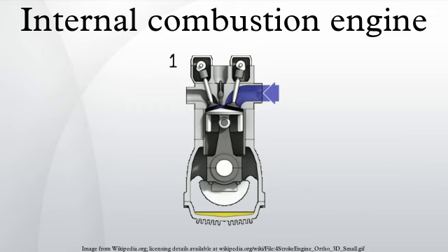Gasoline engines take in a mixture of air and gasoline and compress it to not more than 12.8 bar. When the mixture is compressed, as the piston approaches the cylinder head and maximum stroke, a spark plug ignites the mixture. The necessary high voltage, typically 10,000 volts to over 30,000 volts, is supplied by an induction coil or transformer. The induction coil is a flyback system, using interruption of electrical primary system current through some type of synchronized interrupter. The interrupter can be either contact points or a power transistor.